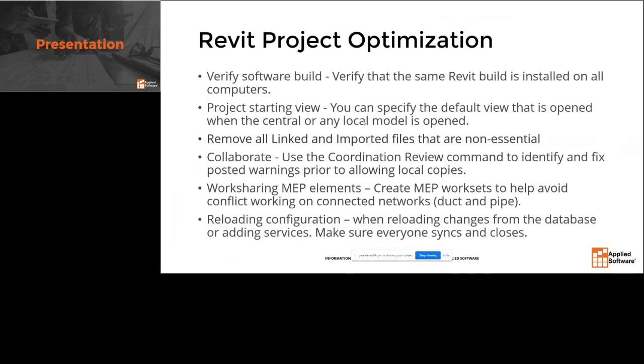Of course, when you're in a Revit project to optimize performance, you want to remove all linked or non-essential links and imports, right? One thing with fabrication, say you're getting the design intent model and you're working directly in it using the transfer project standards like I showed you. But in that CAD file, you didn't know that they exploded like 10 or 20 different CAD files, and there's just thousands of elements all over the place in Revit.